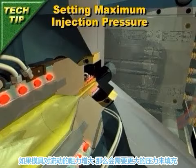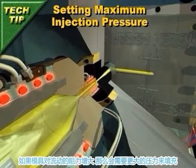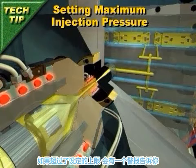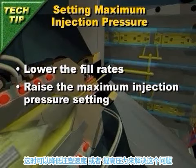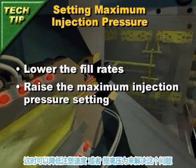If the cavity filling resistance increases, the machine requires more hydraulic injection pressure to fill the cavity at the set rate. If the asked for pressure is higher than the maximum pressure setting, an alarm will be triggered to alert you to the problem. You may have to lower the fill rates or raise the maximum injection pressure setting to fix the problem.